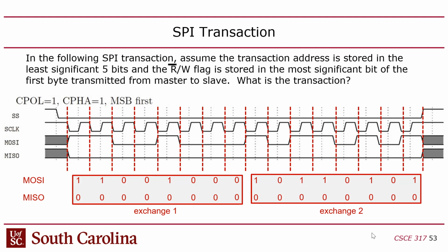The way it's set up, the dotted lines on the waveform are just a guide to show you how wide a clock cycle is, but you don't really know how that lines up with when you're supposed to be reading the data until you look at the settings on the channel, right? So then I show basically just MOSI, MISO, and note what those bits are. Unfortunately, that's really the only way to do it. You have to just work through and mark what these are.